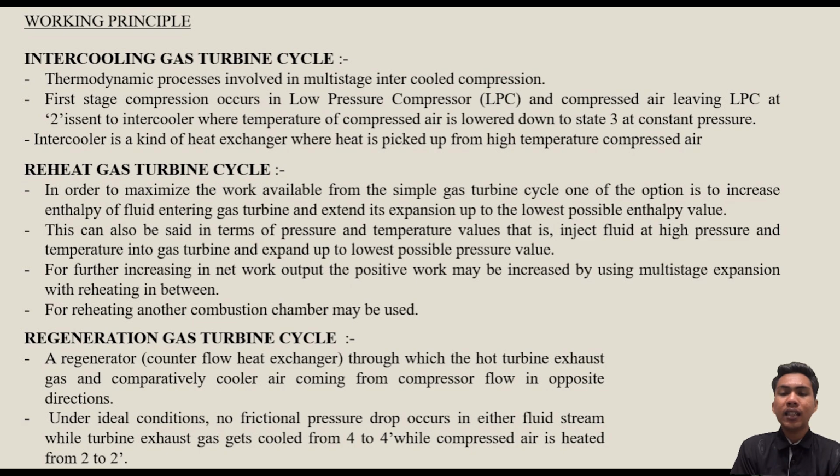Next is the reheat gas turbine cycle. In order to maximize the work available from the simple gas turbine cycle, one of the options is to increase the enthalpy of the fluid entering the gas turbine and extend its expansion up to the lowest possible enthalpy value. This can also be said in terms of pressure and temperature values, that is, inject fluid at high pressure and temperature.